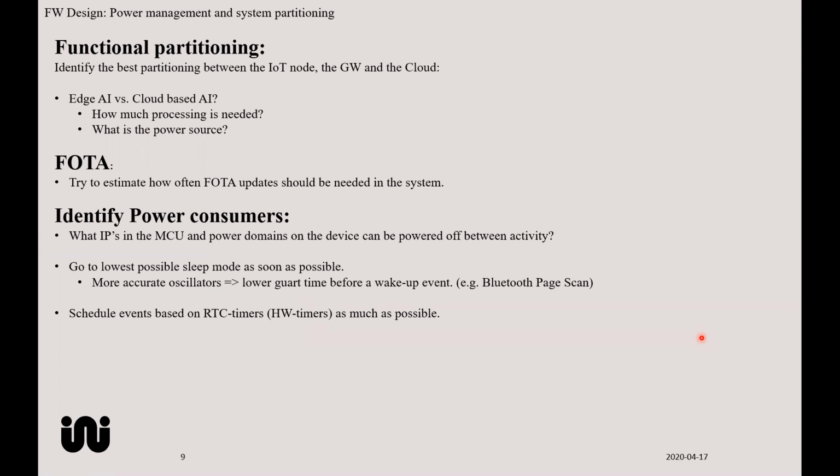Schedule events based on RTC timers or any other hardware timer as much as possible. I think the RTC timer is super efficient when you talk about IoT systems, because in many IoT systems you're monitoring some very slow activity. Could be temperature monitoring, could be moisture, could be whatever, and you shouldn't have a software timer running to wake up and do things on that slow period of time. So keep RTC timers running and try to power off as much as possible.